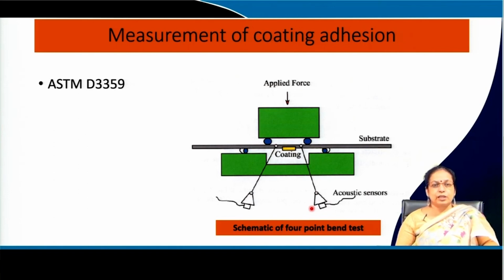In the case of a barrier layer, for example, the environment consists of a lot of corrosive species or other species which are not good for the surface. So we apply another layer on the surface which is very compatible with the environment, so that the environment does not react on the surface anymore. For example, take one case of mild steel and the other case of 304 stainless steel. In mild steel, if the environment is highly corrosive, particularly if it contains a lot of water or water molecules or other species, then naturally there will be reaction of the mild steel with the environment and formation of a ferrous oxide layer, which is highly loose and porous in nature, and hence not good. So there is degradation of the surface in the environment.